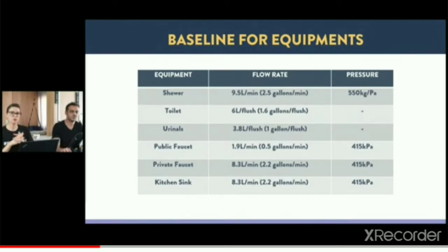And when it comes to faucets, when you're looking into public faucets, I have to share with you an experience: it's not just for you to spec something that is 1.9 liters per minute, and you have the touch timer where you will have the sensor. It's understanding maintenance. I had the pleasure to measure over 200 faucets in an industry.